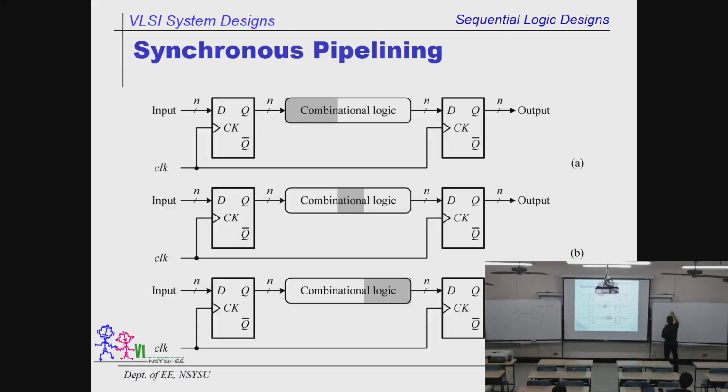And you have something in the middle, and this is a D flip-flop, input to the output, just like the one on the top. And you find out the feature of this design is that we can divide it into several stages, and then they can run the operation in parallel. Because this is a very long delay, and they can be partitionable. If this is the case, for example, the addition or the data conversion, we can do that.